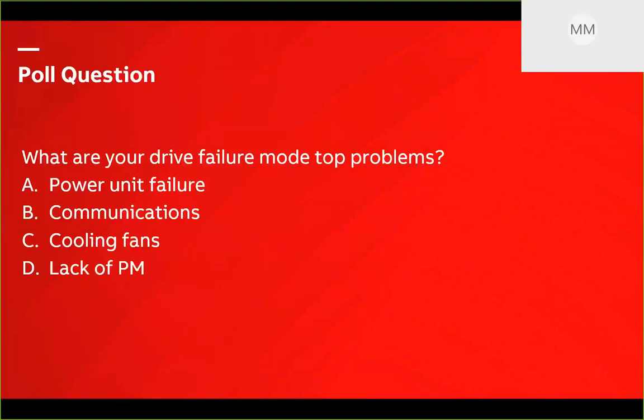When we roll our modules in and out, there's a spring tension back there, and over time that can wear out, and that should be looked at periodically, maybe annually or semi-annually. I think we have some pictures of that to help people here in a second.